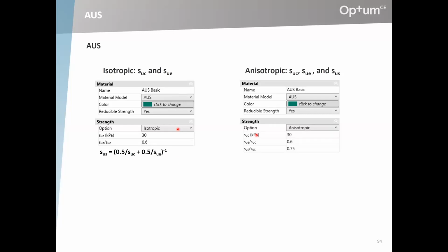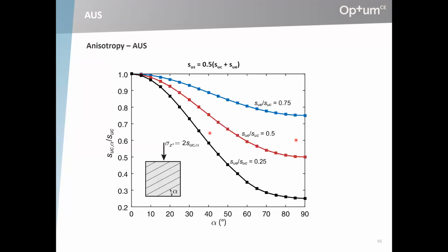For normal clays, let's say clays that are not heavily anisotropic, I would think this is the way to go. And then if you have something special, the LAD data would fit this, this would be appropriate for the LAD data. The Norwegian clays are sort of over here. Then you can do a virtual version of the test that I showed you before, of cutting samples out of a larger sample, and I have some examples here.